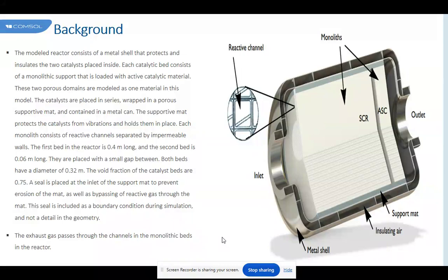Analysis of the effect of substrate material on the steady state and transient performance of monolith reactors. We studied the effect of the substrate material, ceramic versus metallic, on the steady state and transient performance of monolithic reactors using a one-dimensional two-phase model with position-dependent transfer coefficients. When the operation of the reactor is on the ignited branch, it is shown that the monoliths with metallic substrate clearly lead to a superior steady-state performance compared to those with ceramic substrate.